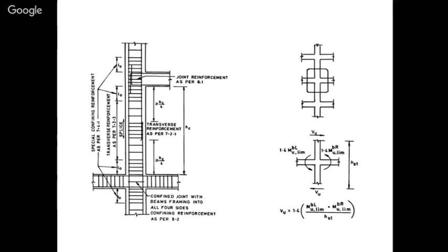The vertical element is the column portion and the horizontal element is the beam portion. Now you can see how the joint detailing is recommended in the IS code. This recommendation is over a small length, not throughout the column. You can see in this image they have marked L0, which is the hinge length in the column. Up to this length, we have to go for closer stirrup spacing, which will allow the entire structure to deform as well as to rotate during large deformation.